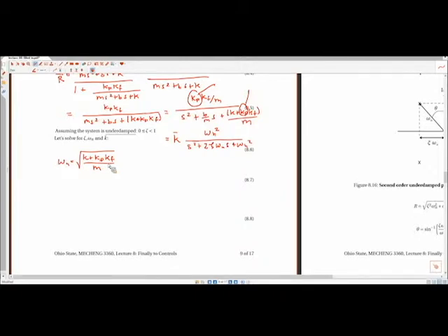So even systems that are naturally very well damped, like where the plant has a lot of damping in it, will result in underdamped systems. And we'll talk about this a lot. We'll show how pretty much every system is going to look like a second order underdamped system. For a system to be in a feedback loop and still be overdamped, you have to be trying to move something like concrete. Something has to have a lot of damping for that to happen.